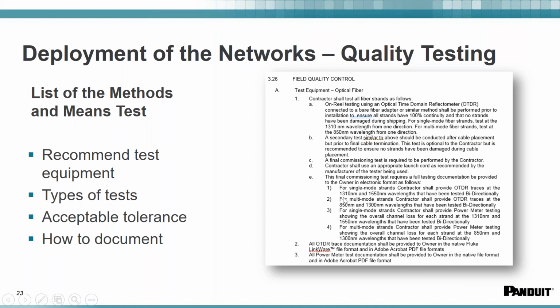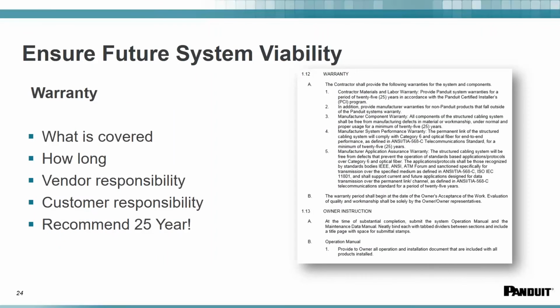And similarly, when you're doing the viability testing, so you've got all of your test results, you now have to have a set of guidelines that says, look, I designed a system, I tested it, I know it passes the limits for my communication. I know that the media chosen abide by the TIA-1005 specs and all of the MICE categorization for what type of cables, what type of connectors.